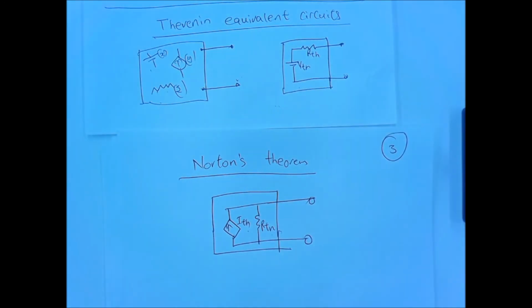How would you measure this R Thevenin? Disconnect all voltage sources and unplug all the current sources, and measure the resistance. The same exact way you do in the case of the Thevenin equivalent.